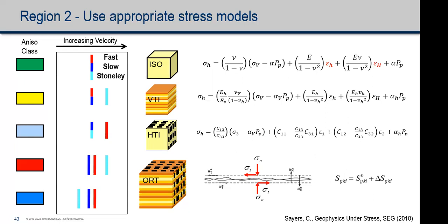Regarding the behavior, since realizing that the rock is in the failed state, what is your thought about the possibility, at a specific location, to stop the tool, continue the measurement, increase the pressure inside the wellbore to stress the rock, and then release the pressure to unstress the rock, look at the difference, and try to use the local modulus of loading and unloading in order to make your calculations? What are your thoughts about this?